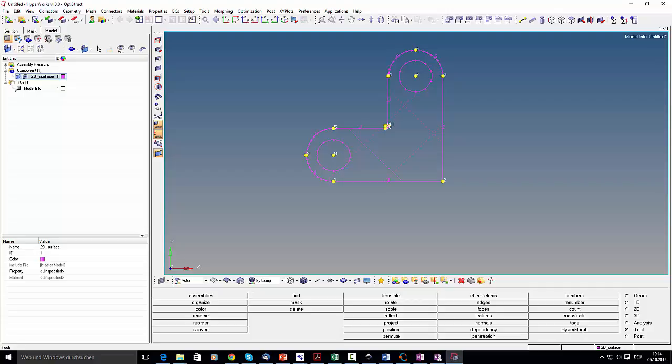So now we have the geometry, but we want to generate fixed points. It means where we can select the mesh density, where we can select certain identity, where the surface or the mesh later doesn't forget that these points existed before. Actually, it's not points in this notation of Altair, it's nodes, and we are generating now fixed points. Okay, how we are going to do that?